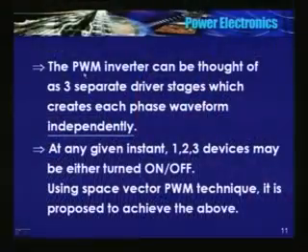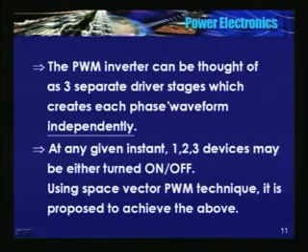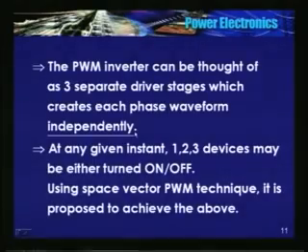I will repeat, a PWM inverter can be thought of as 3 separate driver stages, in the sense there are 3 independent legs. I can control them independently, and they create the phase waveform independently. While controlling phase A, we do not bother about what happens in phase B and phase C. That is what we did in the sinusoidal PWM technique.